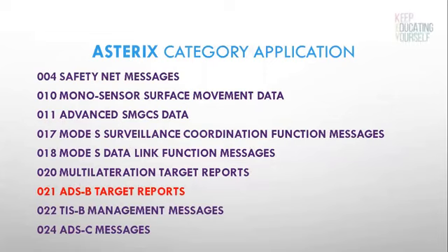ASTERIX category application: 004 is safety net messages, 011 is advanced surface movement guidance and control system, 021 is ADS-B target reports, and so on.